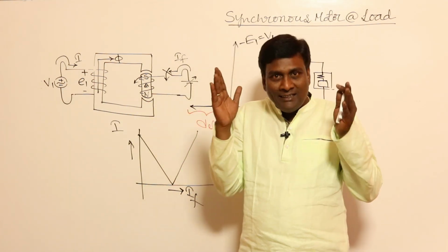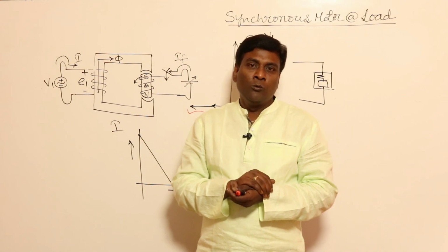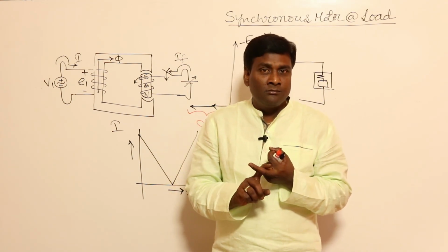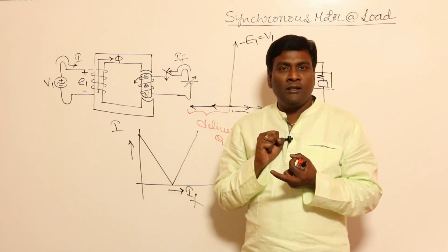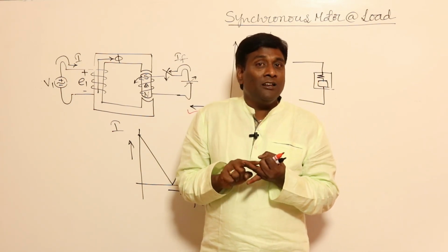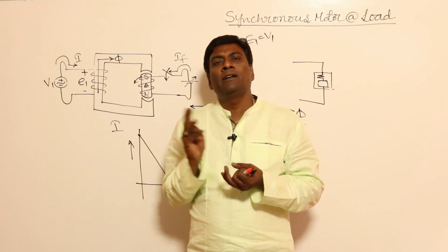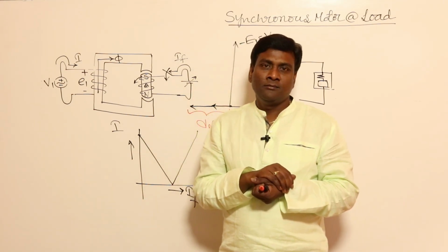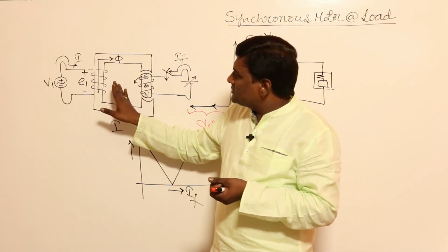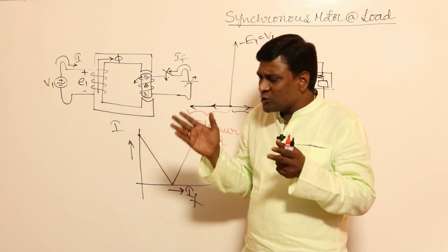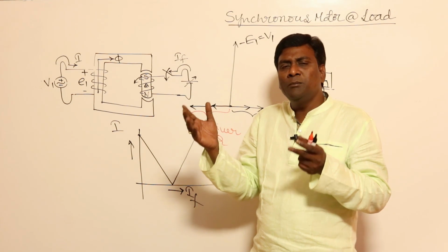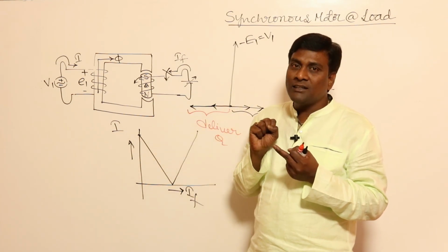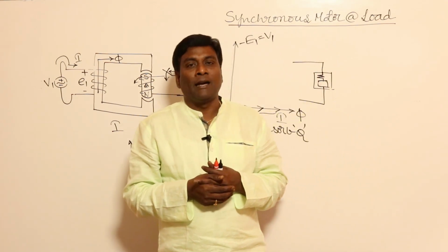So we can say that the motor, to set up the flux, will take reactive power. To kill the flux, it will operate at leading conditions such that the motor will deliver reactive power. Getting my point, right? Reactive power previously we discussed in a different way, but now, to set up the flux, reactive power will be taken. To kill the flux, reactive power will be supplied back.